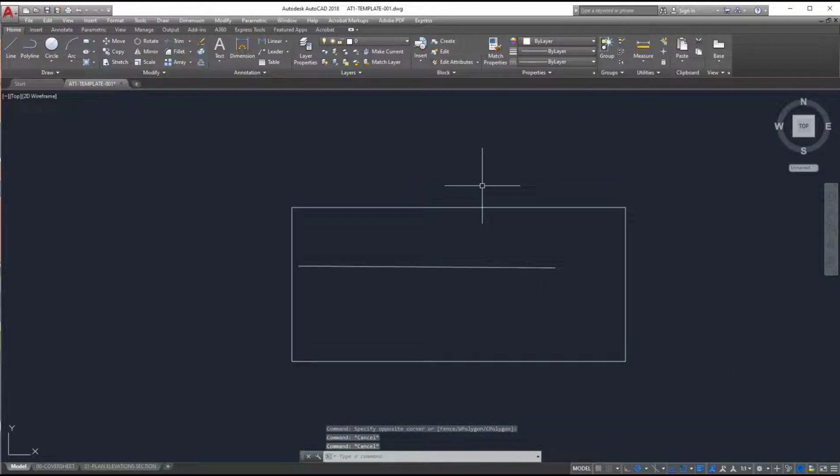CAD is also auto multiple select. So what that means is as I click on multiple items, it will just keep picking up more items. I don't have to hold down shift or control or anything like that. In fact, if I want to deselect items, I can hold down shift and I'll minimize or deselect items. So to select them, I'm not touching anything, just clicking on them. To deselect, holding down shift, and this allows me to deselect individual items. Otherwise, what will happen is if I select these and I find out I actually don't want this line in the middle, if I hit escape, it will deselect all items.